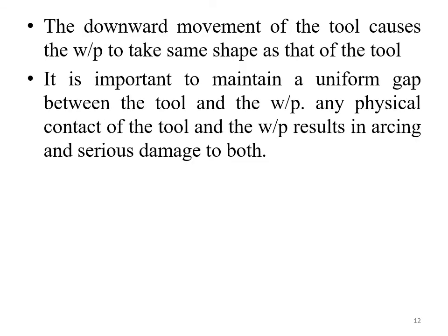Further, the downward movement of the tool causes the workpiece to take the same shape as that of the tool, and it is highly important to maintain a uniform gap, without which a spark or arcing may occur, and this will cause serious damage to both the tool and the workpiece.